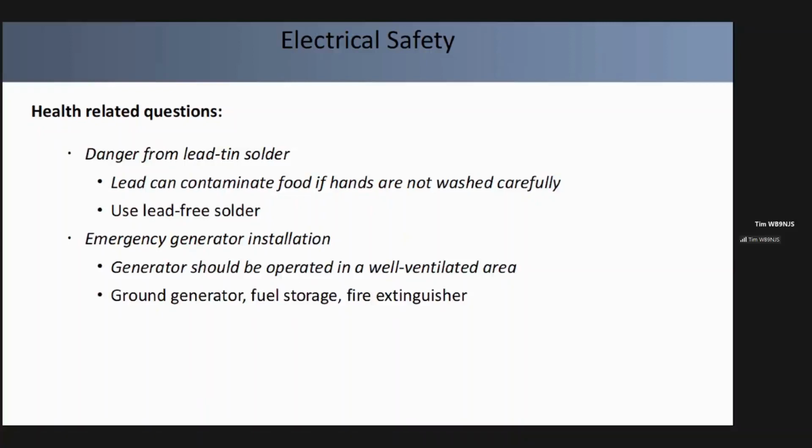Another thing I recommend, it's kind of in the question, kind of not, it's there as wrong answers. For my personal generator at home, you'll find the instructions, along with operating in a well ventilated area, will say that the generator should be tied to a ground rod. There's a ground connector on every generator I've seen.